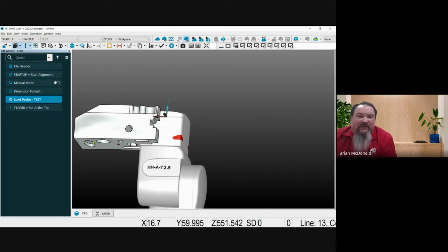One thing, if you break a stylus and you need to replace it, that goes back to the cal sphere. Has the tool been moved or not? If the tool hasn't been moved, replace your styli. Say no, happy days, everything's great. If you have moved the cal sphere, you need to go back to that primary probe, calibrate it at A0, B0, and then calibrate the replaced probe, and then everything's linked back together.